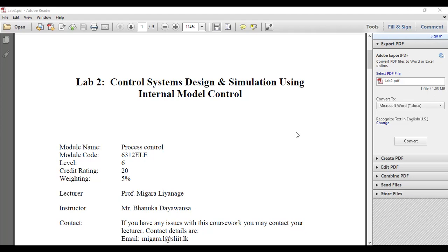When we were discussing the Ziegler-Nichols method, I discussed some of the advantages and disadvantages. One of the disadvantages was that it was not very robust. It was not very mathematically complete. You just use the trial and error method to find the KP, right? Then you use the KP as your critical gain, and your critical period, everything is based on whatever KP value you get by guessing using trial and error to obtain your system in marginal stability.